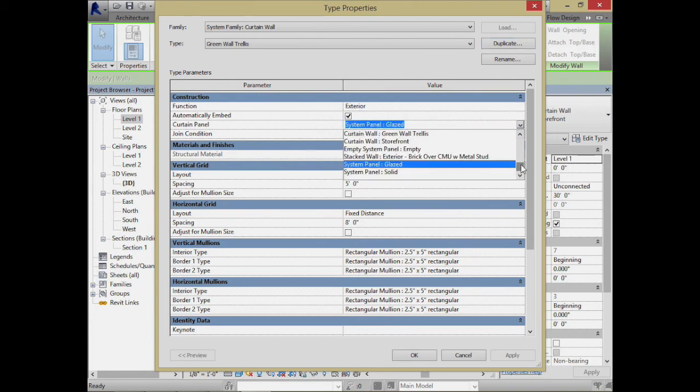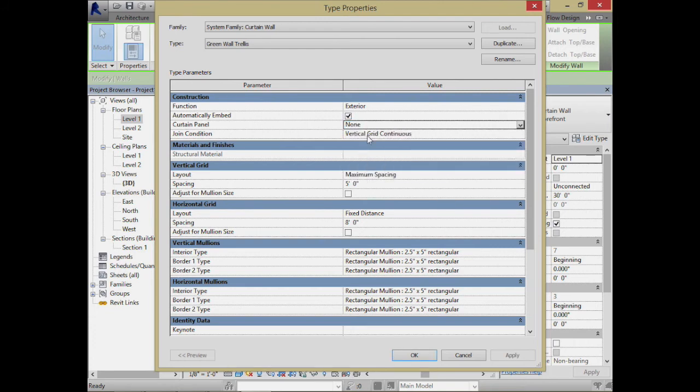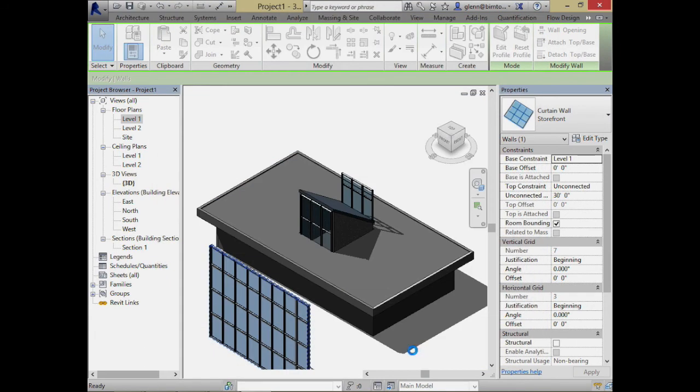I tried to do this once for you before, and let's see if I get it right this time. I think it's there where I say none. It won't be, but that's where I'm going to guess. I'm going to give a spacing of about every 8 inches by every 8 inches. Now it's just an issue of whatever these mullions, these cross sections, are right now. Right now it's 2.5 by 5, and let's just test that. You'll find that I often test things because I often guess wrong, and I get there incrementally.